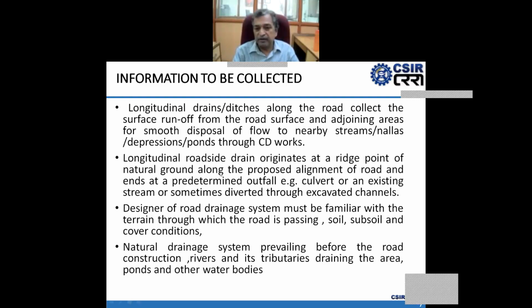A longitudinal roadside drain originates at a high point of natural ground along the proposed alignment of the road and ends at a predetermined outfall, that may be a culvert or existing stream, or sometimes diverted through an excavated channel.